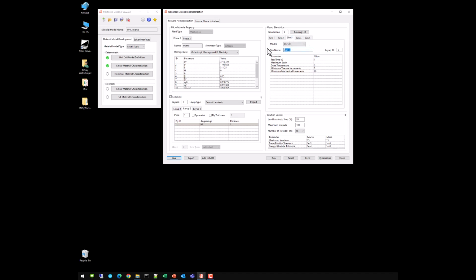My third simulation will be my in-plane shear. That is my plus minus 45. So that's laminate 3. Laminate 3 is my plus minus 45, as you see here. We'll pull that to 5%. It's much more ductile, can go quite a bit farther. Still the same, minus 200 delta T, 10 thermal increments, and 500 mechanical increments. We always want to go in about 100 microstrain mechanical increments.